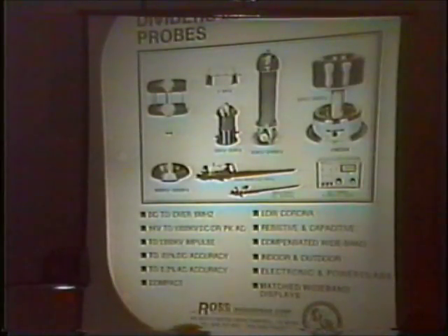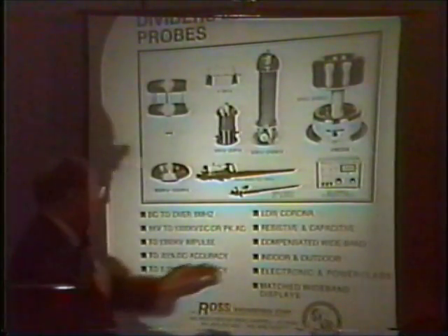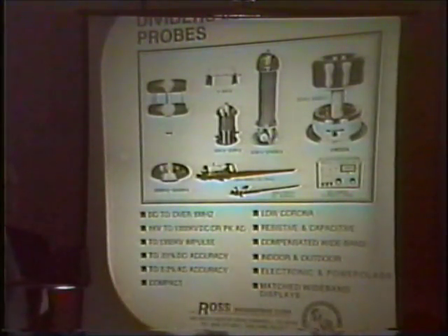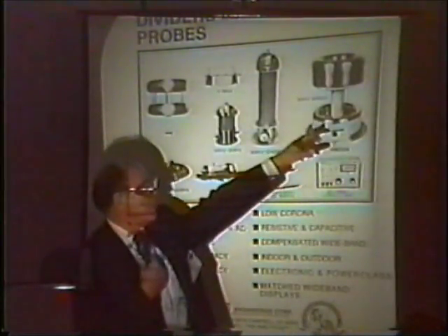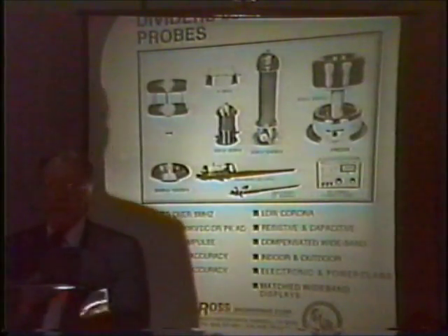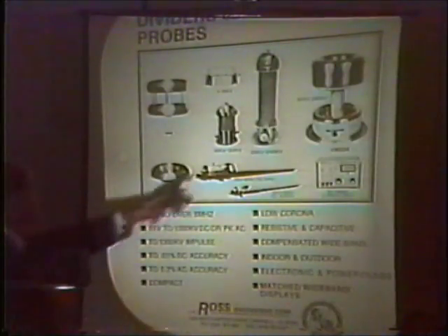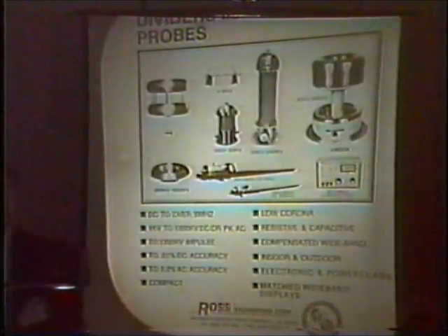But the general idea on this is to get your division on your electrical output down to where you can measure it with your meters. And the type of device that you would end up measuring with would be something like this, and I'm going to show you more details on that in a moment. But this with a proper setup like that can go up to over 1,000,000 volts. But the 1,000,000 volt unit is taller than this room here. It's built up in sections. I'll show you one of those in a little bit.